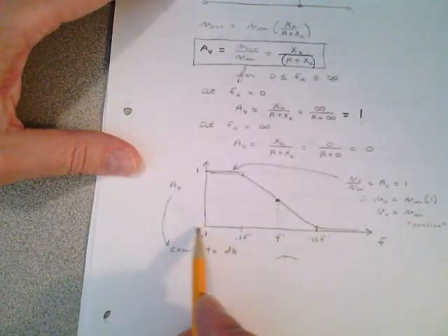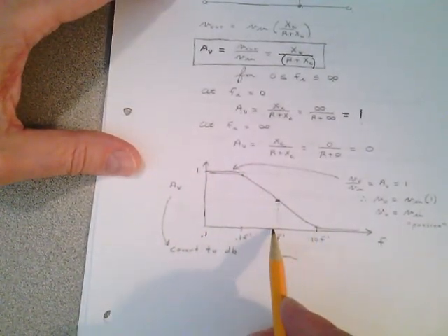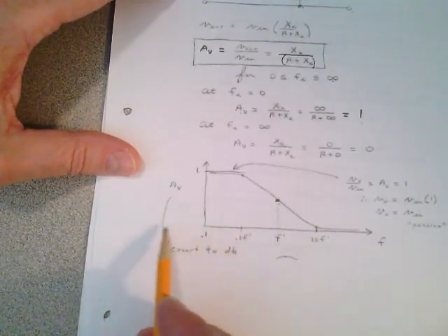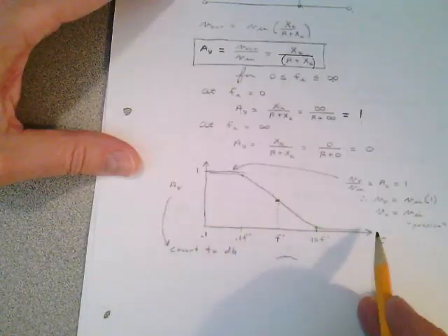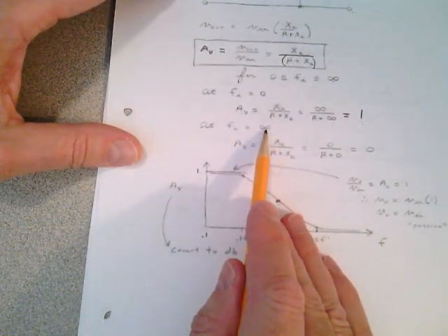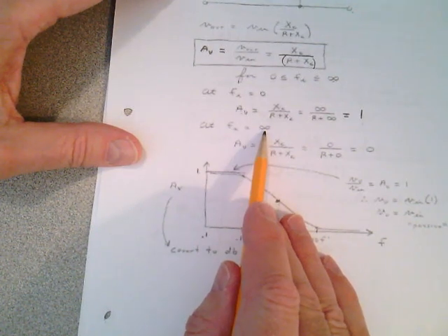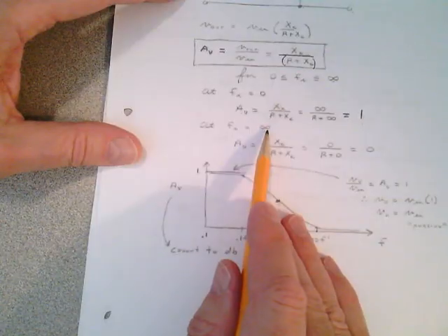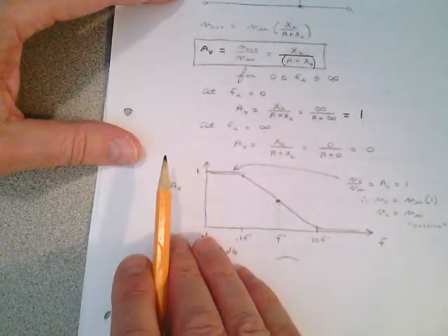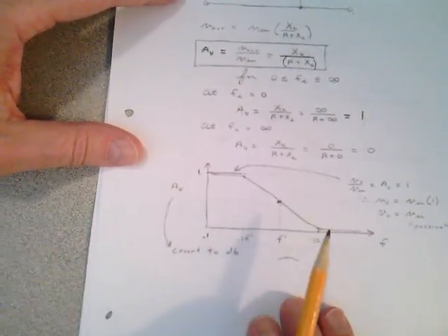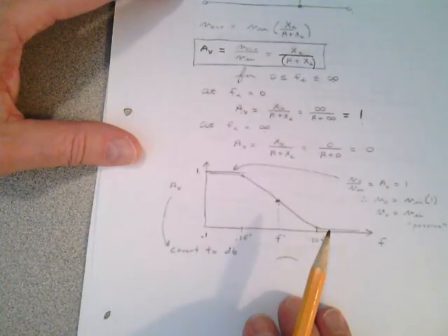No, DC isn't shown here. These frequencies get smaller and smaller, but you just approach 0 frequency. There's no label of 0 frequency on this axis at all. And as you go in this direction, the frequency gets higher. Well, let's take a look at frequencies approaching infinity. Well, we know at very, very high frequencies, the capacitor looks like a short circuit. We discussed that in the past too. That's when you first close the switch, remember? It looks like a short. When you first close that switch, that's a step function. That's a very, very high frequency component.